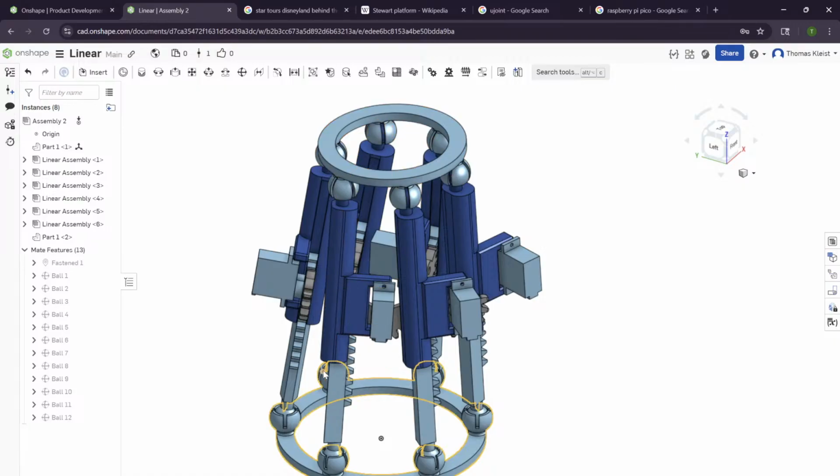I'll just need to come up with a way to 3D print them such that they don't need bearings in every single joint, because a U-joint could use up to 4 bearings, which would be way too much. It has 12 U-joints, so that's 50 bearings, which is too much for this. It would get big and heavy really quick. So we'll work on that.